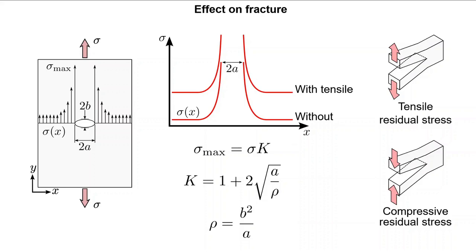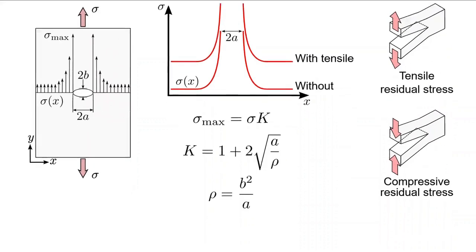suspend it. Therefore, if one can introduce compressive residual stress surrounding a potential stress riser, then the overall performance of the component will improve. For both components that are subject to fatigue and fracture, some industries will pursue secondary surface treatments to create these compressive stresses. For example, some turbine manufacturers will employ laser shock peening on their blades to improve their service lifetimes.